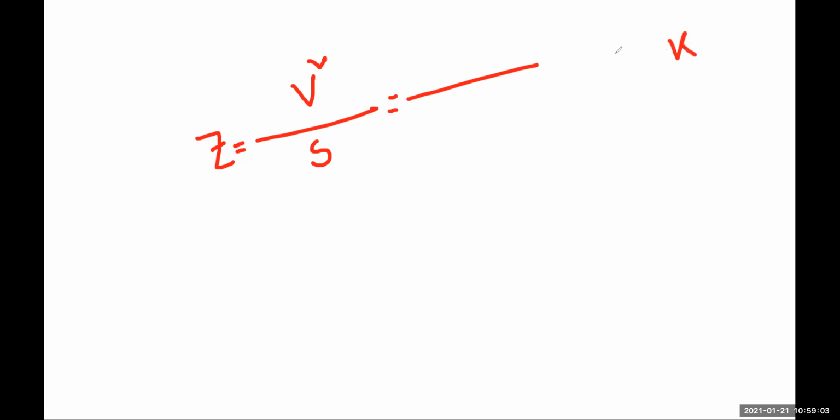Usual unit means what? The upper one, that means Z, will be V squared by S, right? So V should be in volt. If I give something like this, V is equal to 10 kV and your S is equal to 100 MVA, you convert that in your mind, not in your script.